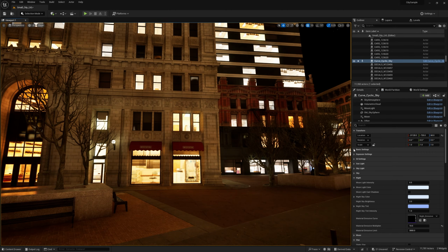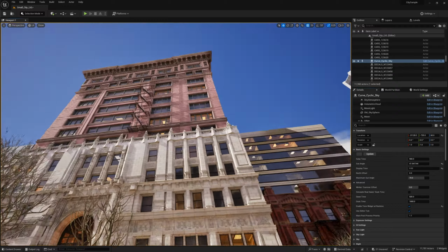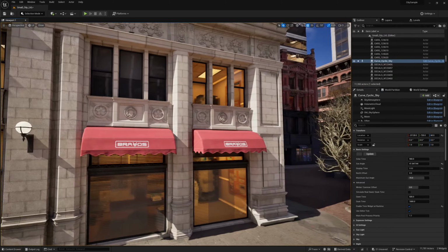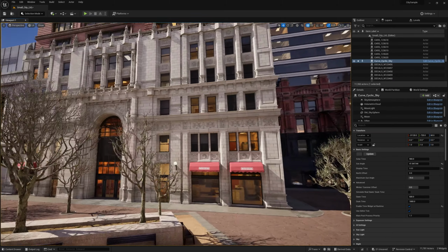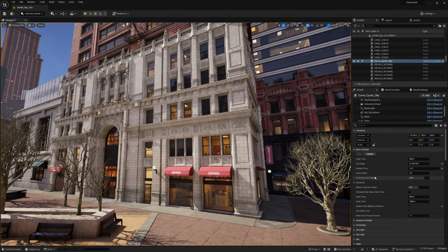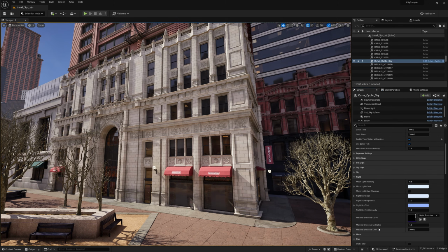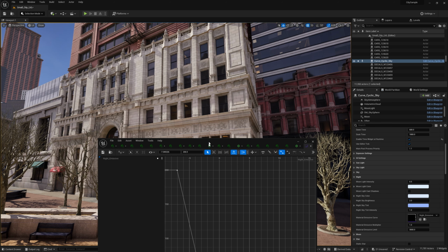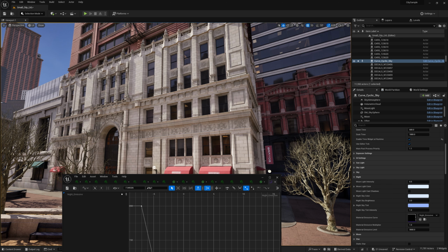When we switch back to daytime, the window's self-illumination brightness during the day looks a bit too bright. This doesn't look like the interior light brightness we'd see from outside during the day. So we cancel this brightness multiplication and use material emissive curve to control the brightness. Double-click to open the curve, find the leftmost point, which represents the night brightness. Let's give it a tenfold multiplication.